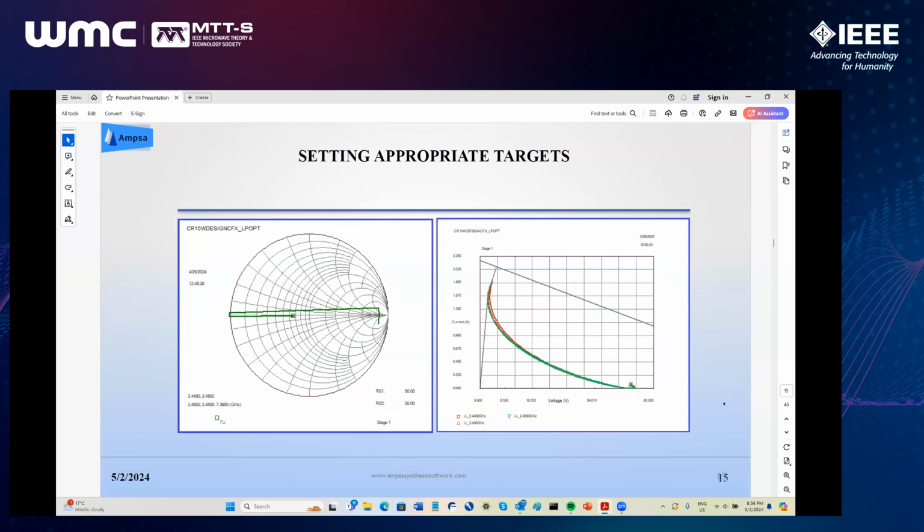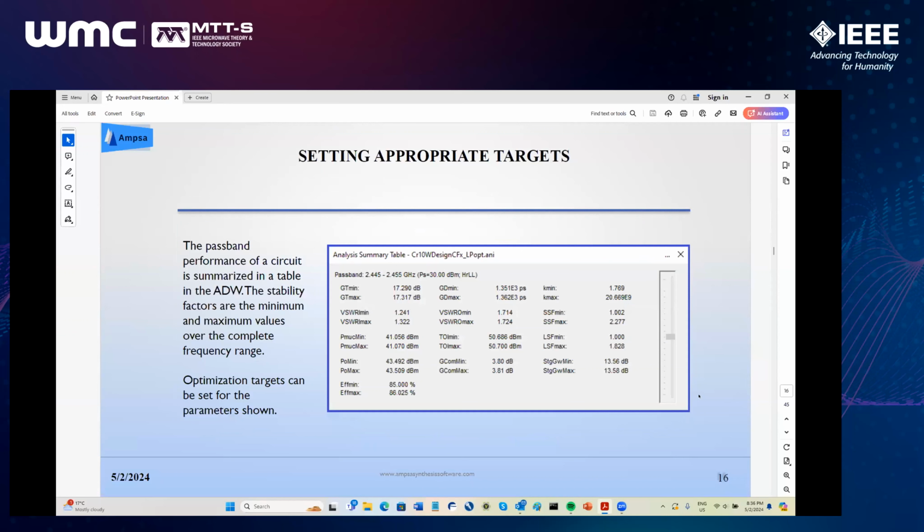Now, interesting, again, we are not usually only interested in power and efficiency. There are many more things that are important. So this is maximum unclipped power. You can see sort of 41 dB. That's where it hits the clipping lines. Then it can go into compression. You can go further, so in that case it can do 2.5 dB more. So that's the compressed power. This is the gain compression.